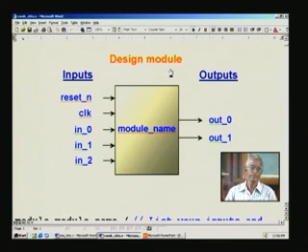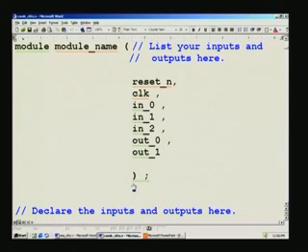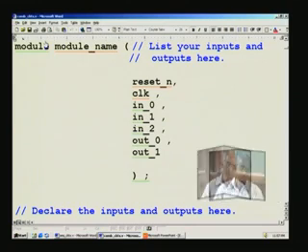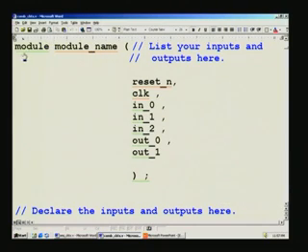And now how to code this in Verilog? So what you see is you start by writing this block on your paper and then go on to code it, and the way to code is right here. See, first we said module name, and that is what appears here, and before that we had to say it is a module, and naturally the whole thing is identified by this module name, which is particular to your design. And what is this? It is a keyword in Verilog to identify there is a module here. So there will be a module here and a corresponding endmodule at the end, which we will see towards the end of this piece.